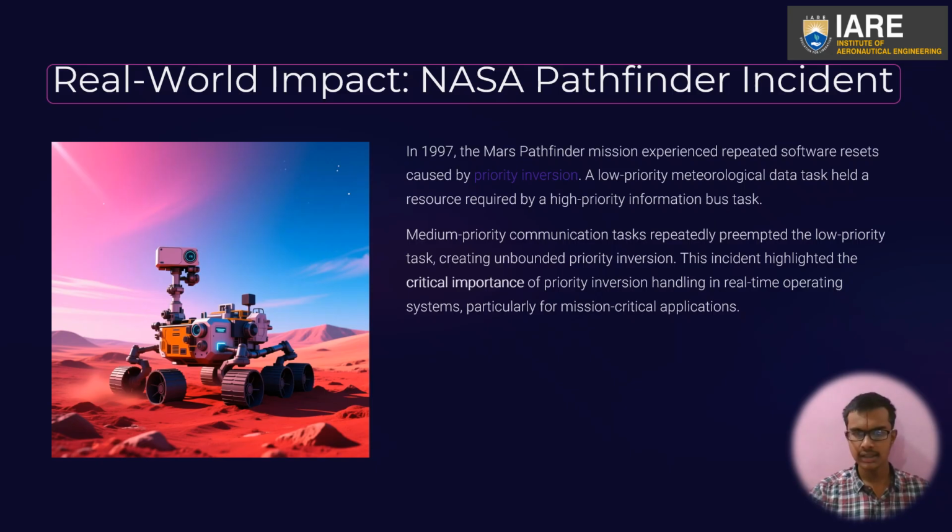the meteorological data task, held a resource required by a high priority information bus task. Medium priority communication tasks repeatedly preempted the low priority task, creating unbounded priority inversion. This incident highlighted the critical importance of priority inversion handling in real-time operating systems, particularly for mission-critical applications.